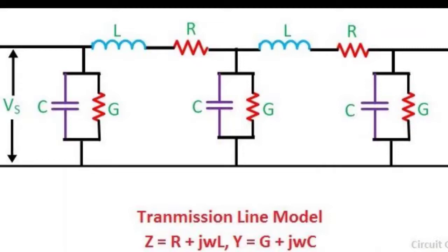And if we talk about line capacitance, in a transmission line, air acts as a dielectric medium. This dielectric medium constitutes the capacitor between the conductors, which stores electrical energy and increases the capacitance of the line. The capacitance of the conductor is defined as the charge per unit of potential difference. The capacitance is negligible in short transmission lines, whereas in long transmission lines it is the most important parameter. It affects the efficiency, voltage regulation, power factor, and stability of the system.